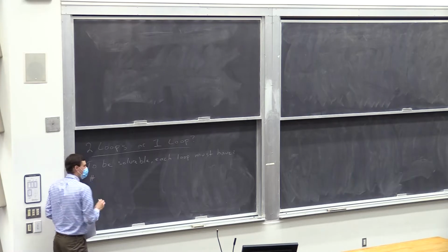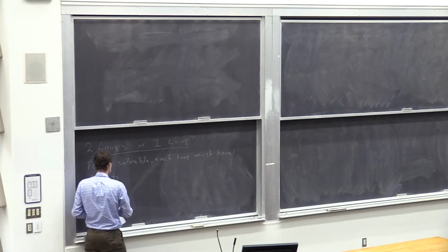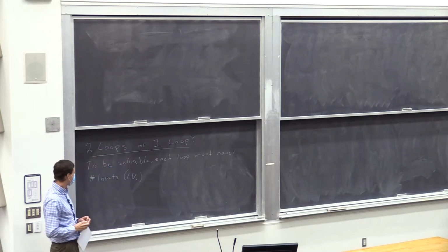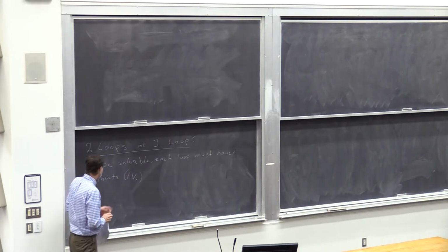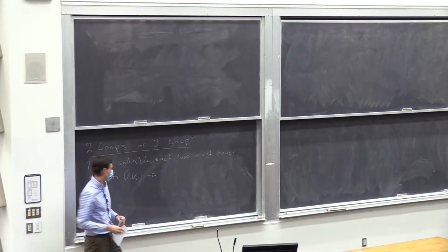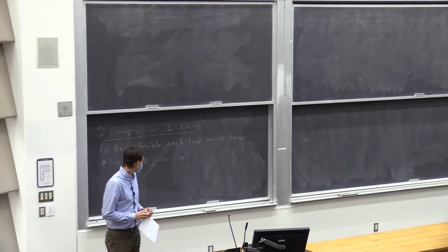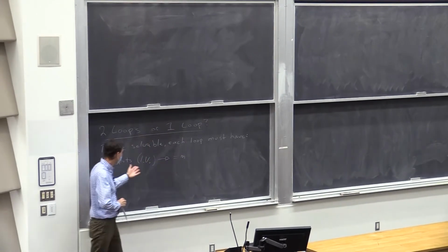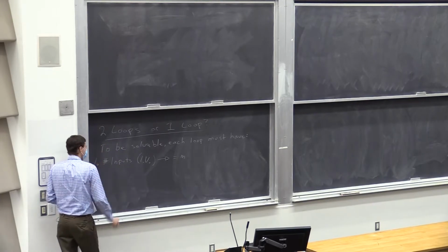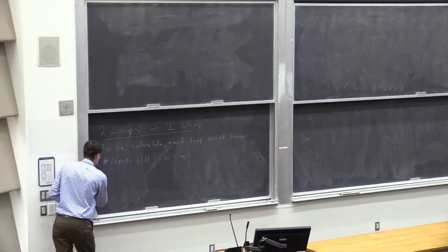So we know that our number of inputs, these are our independent variables. In vector loop language, those are independent variables. We set them independently. They don't depend on anything. Those are the inputs. This needs to equal the mobility of the mechanism. If our mobility is 2 and we only have 1 input, it's not specifying what's happening with that mechanism. Okay, so that's our first criteria. That one should be pretty straightforward. When that one's violated, you'll just see that.